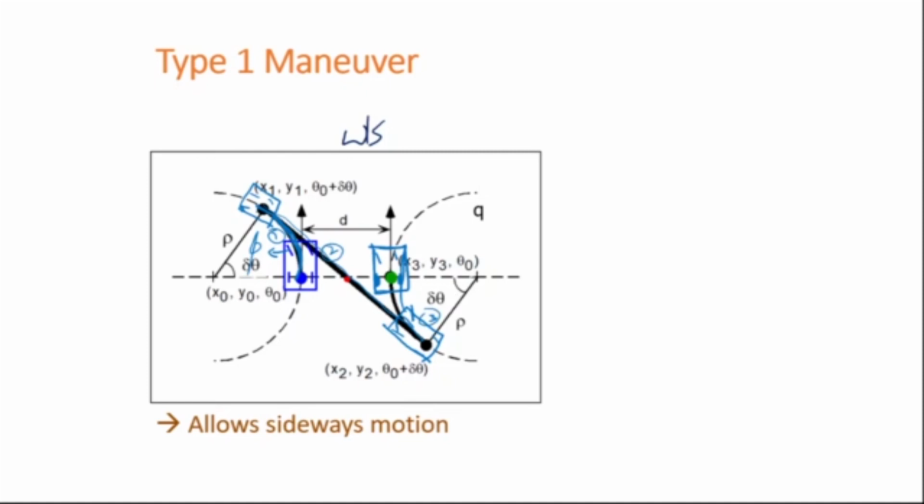Now because the car can have different steering angles, of course there is a limit to that. For different steering angles it can have this kind of a circle, or it can have a slightly wider circle, or maybe a slightly smaller circle, depending on phi, the turning radius. From here it can probably come backward like that and then go again. So by doing this set of motions, the robot can actually go sideways and park wherever it wants, because the system is fully controllable.